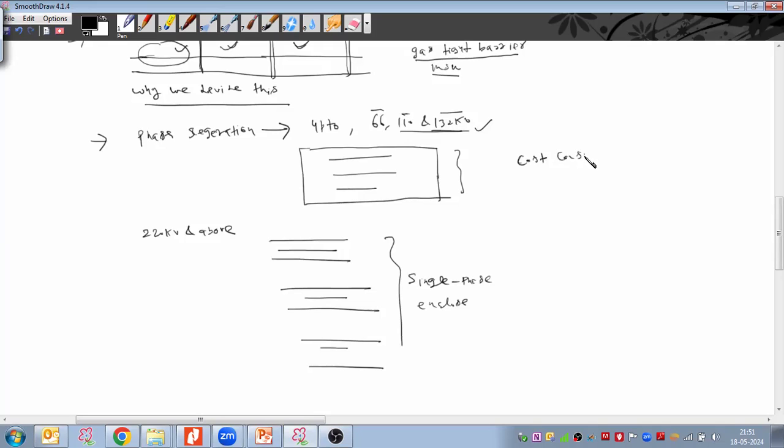So what is the general practice for the general proposal? How do you propose this, generally, as per the regular practice? We propose based on the three phase. Normally we propose three phase for 132 kV or 220 kV, and 400 kV normally single phase. Okay, so you are telling that till 132 kV, and you are adding also 220 kV, right? 220 kV, yes. So in the first attempt you propose the three phase enclosure, right?